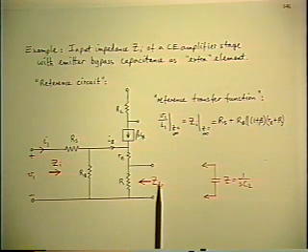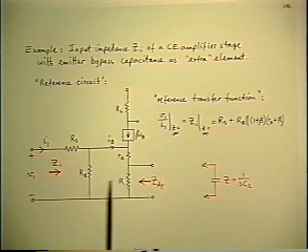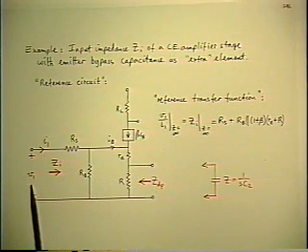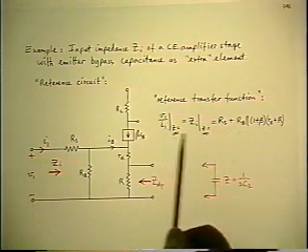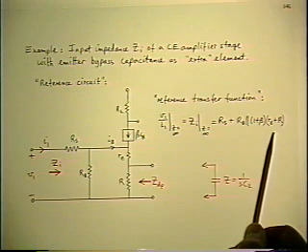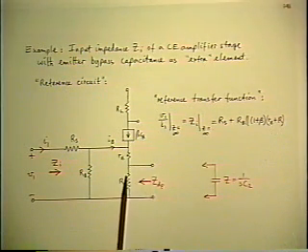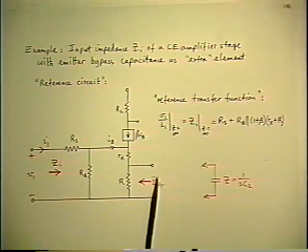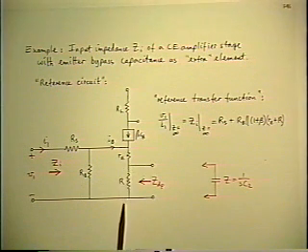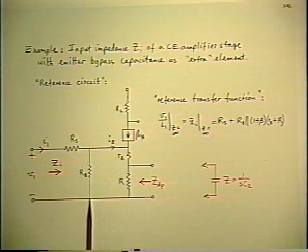And it's a single injection calculation in which the original input of the transfer function is 0. So this is when you have to be careful as to what the input is. The input is I1, because that's the denominator of the transfer function that the theorem is being applied to. So we have to calculate the impedance looking in at these two terminals when I1 is 0. And the answer is, when you look in, you're going to see R in parallel with RE plus the reflected RB.